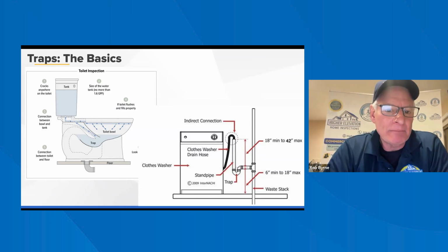Okay, basics. Trap clean out defects, that's pretty obvious. Also, when you have a trap underneath the sink, that becomes your clean out. You can unscrew that and then the trap would dislodge and you can clean out if anything gets stuck in there, hair or anything like that, or stuff that would drop in there. So we've got trap clean out.